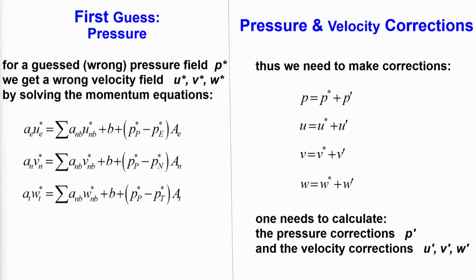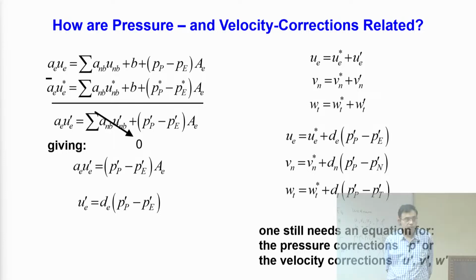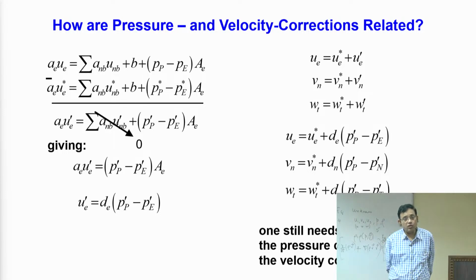So, now the challenge is how do you estimate these corrections? You do not know. To estimate these corrections, even if you do not know anything, say you are solving some equations. We have exhausted the use of the momentum equations, the 3 momentum equations we have used, but the continuity equation is still in our pocket. So, we have to see how we can make use of the continuity equation to make an estimation of these corrections, and the entire way in which the algorithm is developed with that objective is translating into a mathematical form.